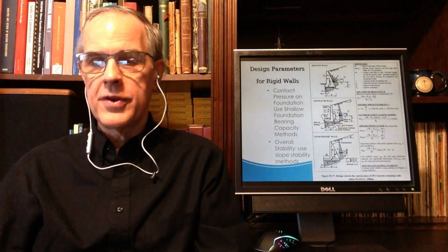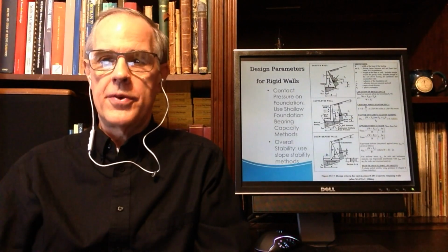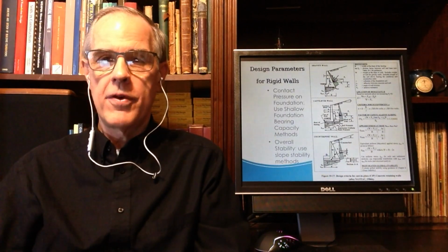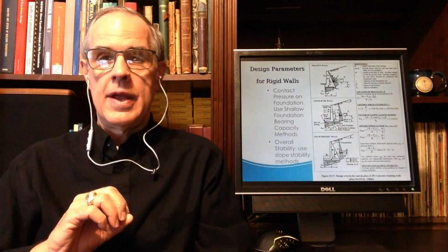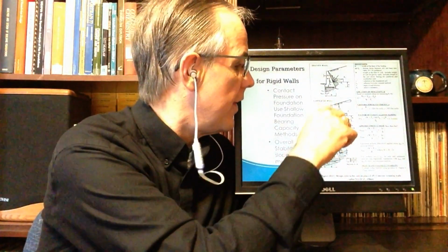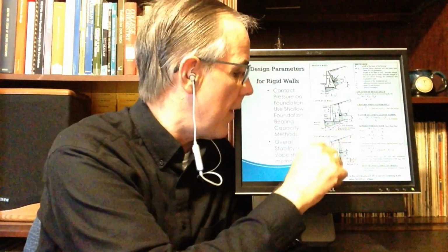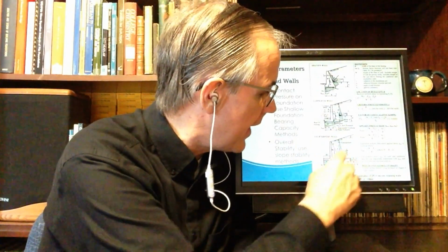So the last one is a counterfort wall. The only difference between a counterfort wall and a cantilever wall is that a counterfort wall attempts to address the problem I just mentioned. It does so by, instead of having just this and then come to the end and go that way, it has some ribs it puts in there, as you see in this little section A-A.